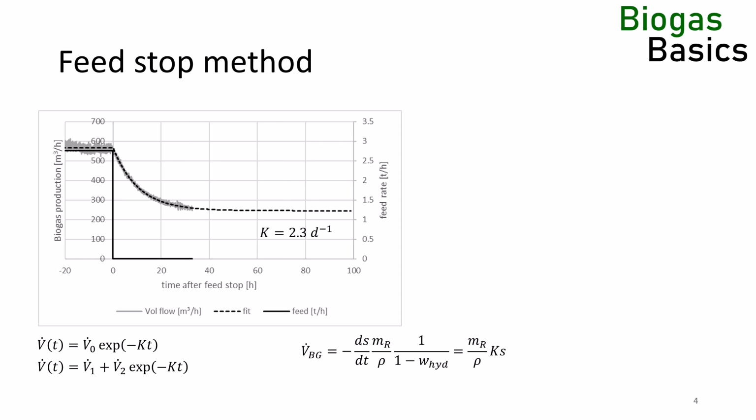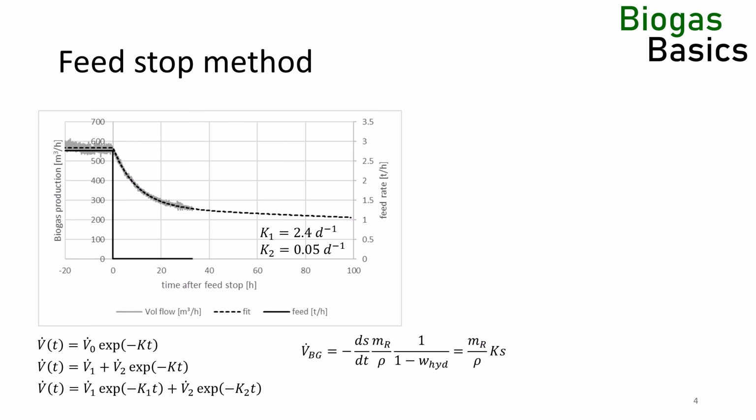The fast and slowly degradable substrate will have roughly the same concentration in the feedstock, but in the reactor the slowly degradable substrate dominates because the fast degradable substrate fraction has already been mostly degraded in the steady state. We can fit the feedstock with the two-fraction model. It is almost identical to the last model, with the exception that for a long-term forecast, the biogas production will drop slightly and will eventually reach 0.